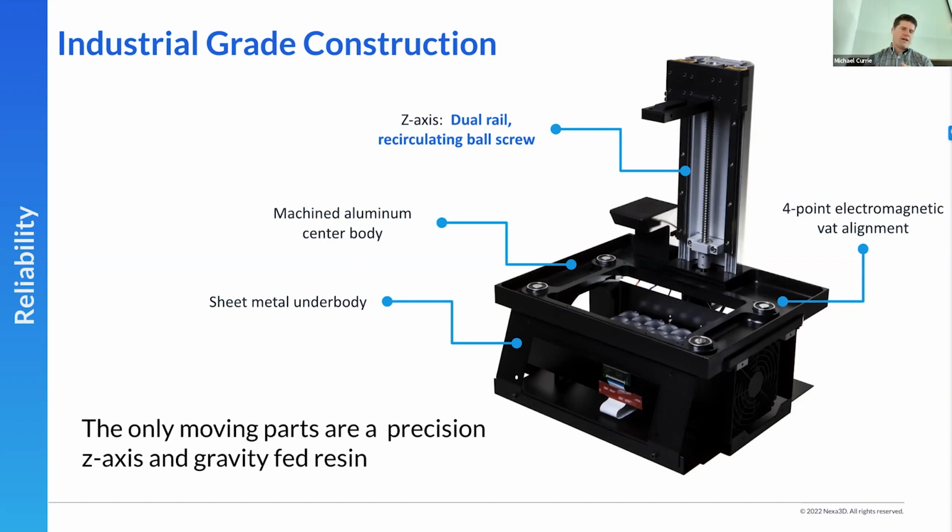And with that, you have a high performance ball screw that is creating the Z-axis. So you want this structure to be as rigid as possible. If you're talking about pixels that are the size of a human hair, you need the entire system to honor that level of resolution and keep things in alignment at that level to get that very precise printing.